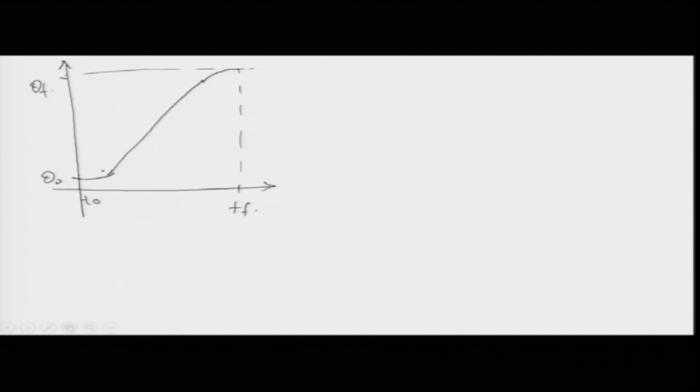Okay, so you understand that. Now, what we are seeing here is that there are 3 parts. There is another part here which is called T b, this is the time of blend. So, the blending path starts from here. This is my blend part, and it stops at this point. So, there is a blend part, then there is a linear part, and then there is a blend part again. This is my linear part which is going straight, and that is my blend part.